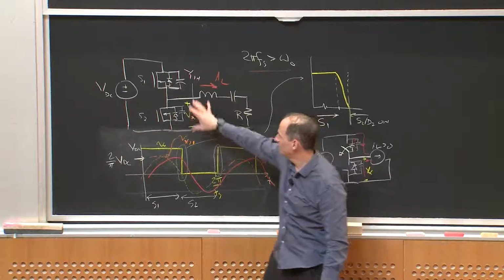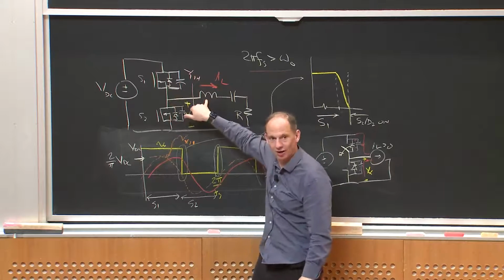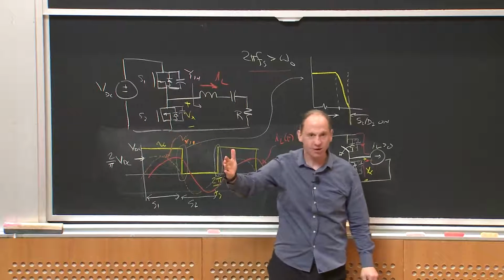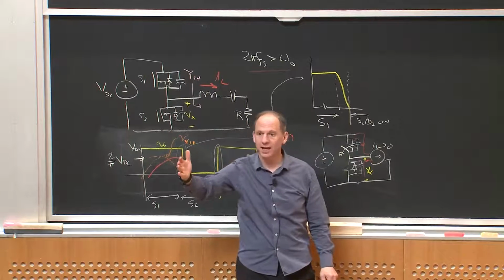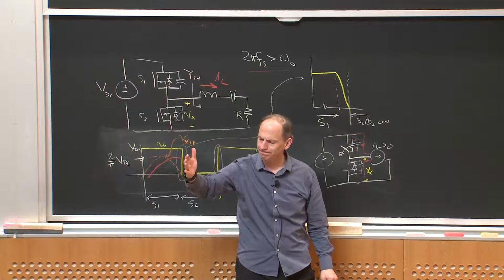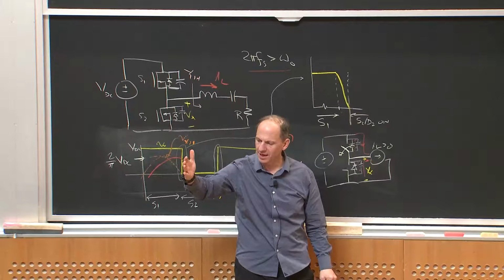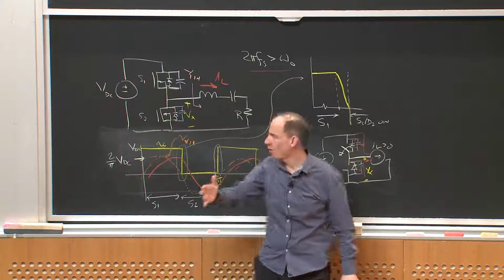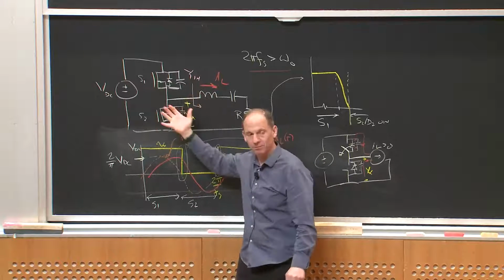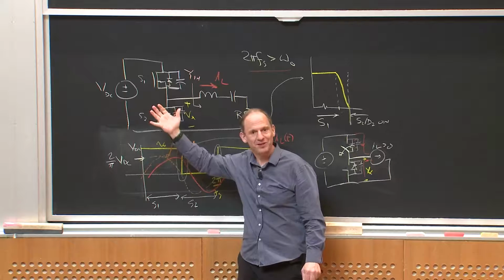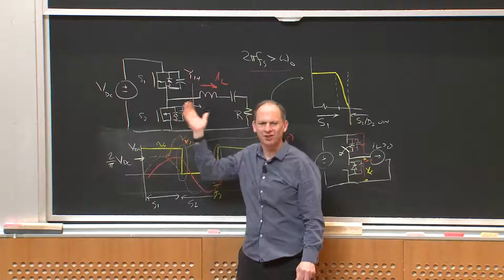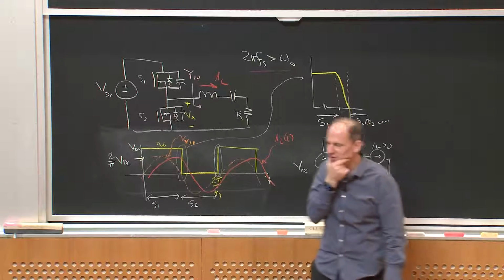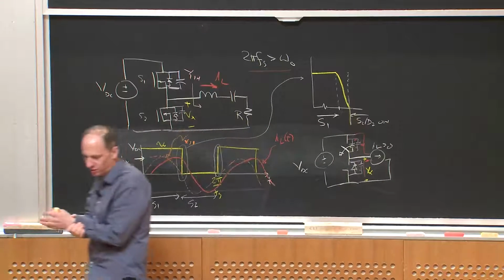But that also means that the device currents, the inductor current and the capacitor current also get lower. So this characteristic has the nice habit that as I'm reducing power, all the currents in my devices and components go down. So I can keep efficiency high as my power gets lower and lower. That's a nice characteristic of a series resonant converter.